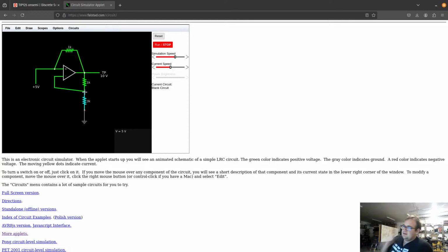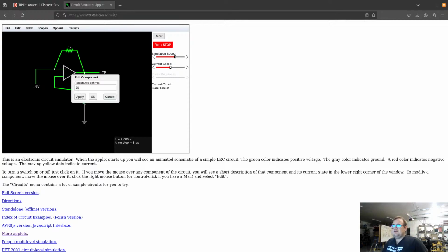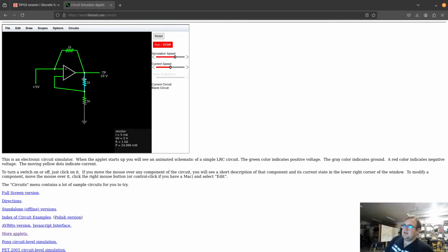So that means there would be 5 divided by 3 would be, frick, why did I make up this one? Let's change this to 5K. Then I don't have to do somewhat complicated math. So then we would have a milliamp going through, since this is 5K, if we have 5 volts here. So 5K, a milliamp. That means 1 volt gets expended across here. So this output will be 6 volts. And then we will just have a single milliamp coming out of here too.